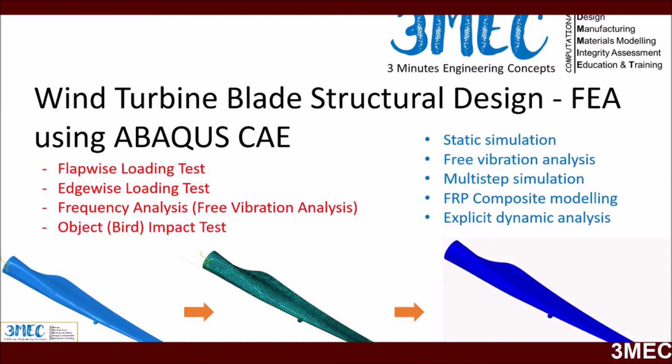By going through these videos, you will learn about static simulations and how to perform free vibration analysis, which is used for natural frequency analysis. You will also learn multi-step simulations, because we have preloading due to edgewise or flapwise loading, so we need to first load the structure, which is step 1, a general step, and then use the free vibration analysis step to find out the natural frequencies of the system.